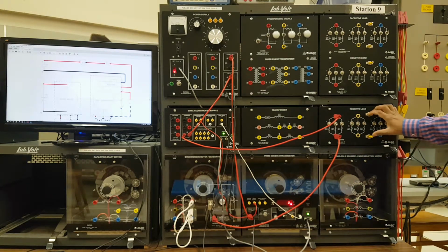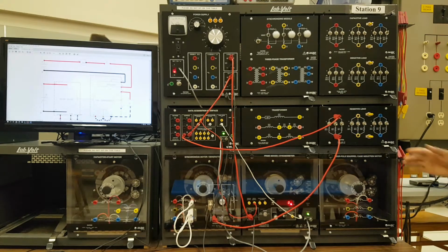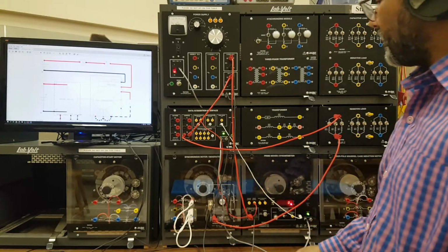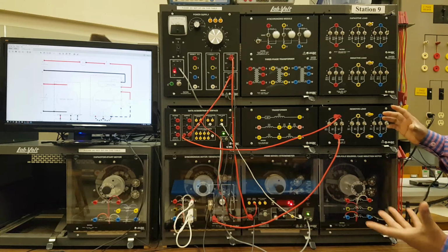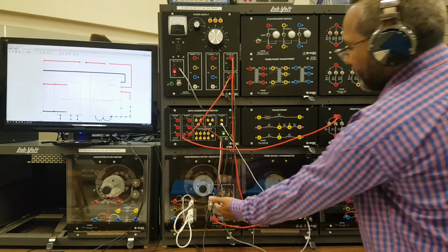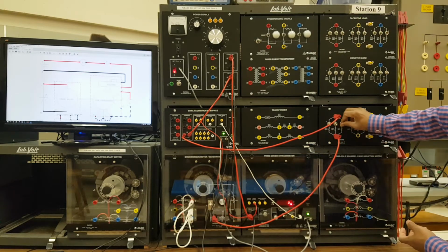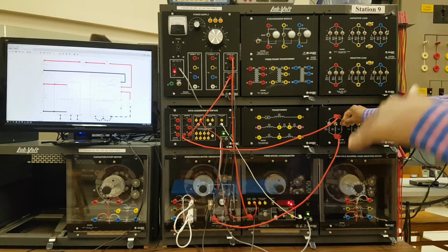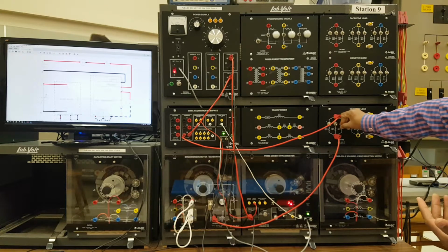We'll turn on both the switches. That way all the 9 resistors are in parallel, and we have a choice to figure out these things. You can notice that the field current can be varied by using this and this. Because we have a fixed resistance, we can have the field current in step-wise or coarse control.